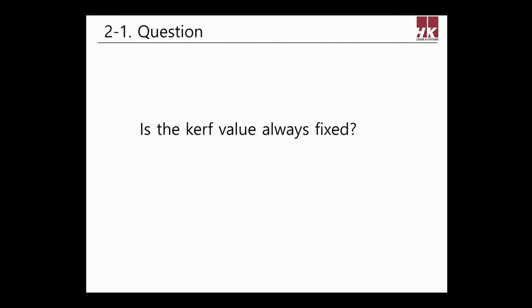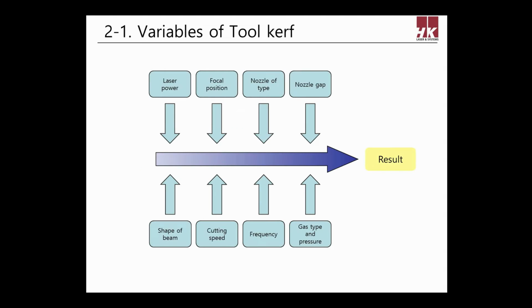Is the kerf value always fixed? As you can see, there are many variables at the end of the laser head, such as power, nozzle size, gap, speed, frequency, and gas pressure, that will affect it.